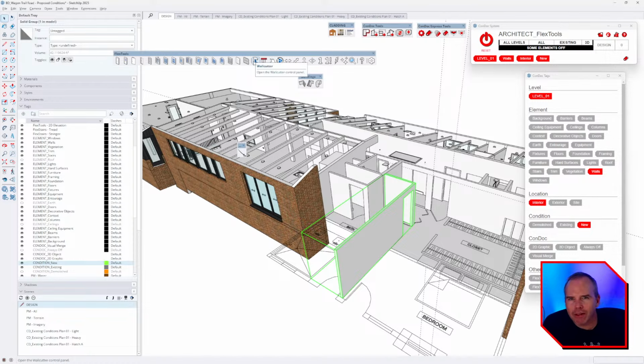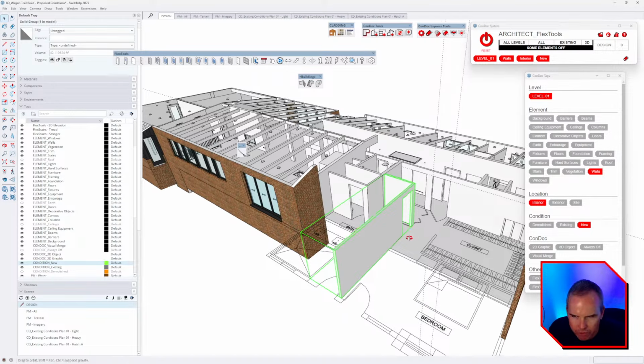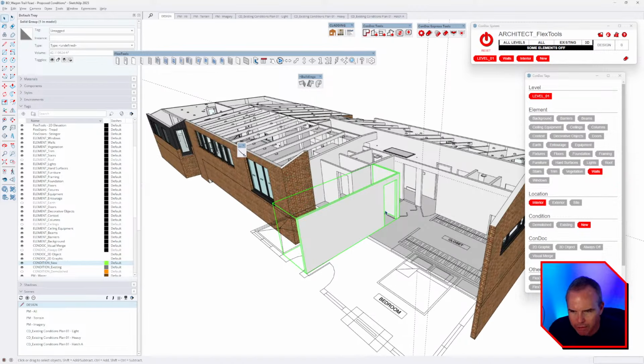So my preference when using the Flex Tools, I love Flex Tools for the doors and windows, and they've got this width, height callout that translates over into LayOut. A lot of good things about it. And there's some other tools that I haven't totally dug into, like their component finder. I've heard a lot of good things about that as well. But as far as the wall cutter goes, it seemed to me it was just easier to cut my openings manually like this, and in the end I was committing those openings anyway.